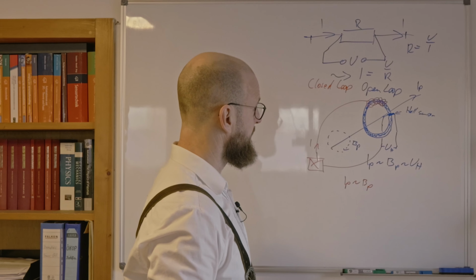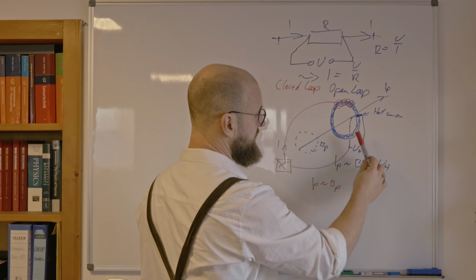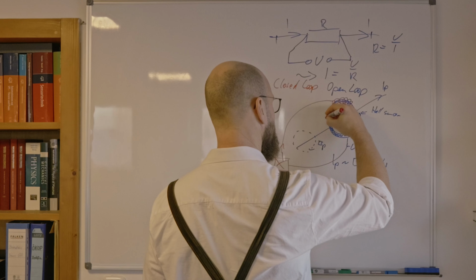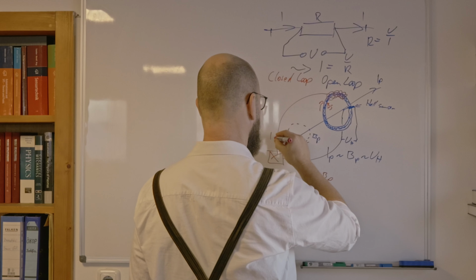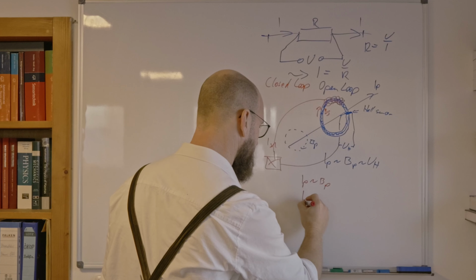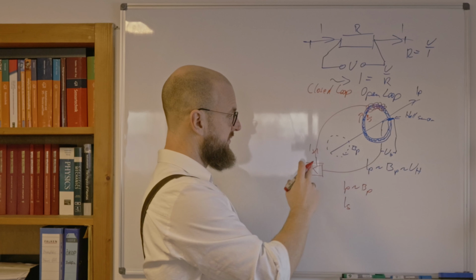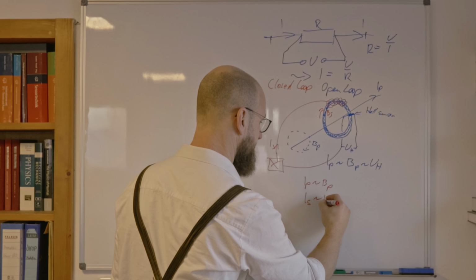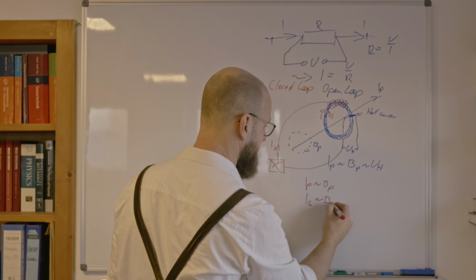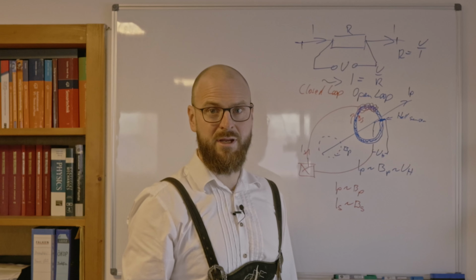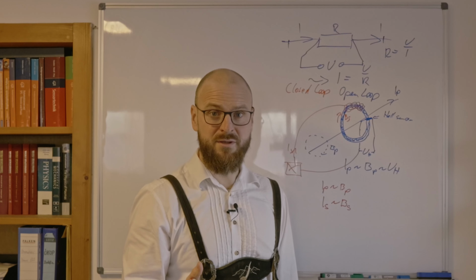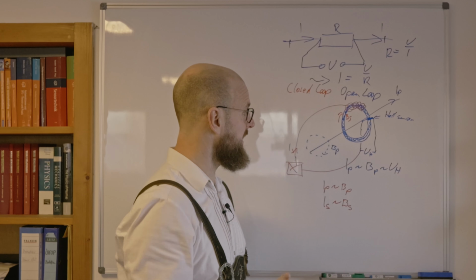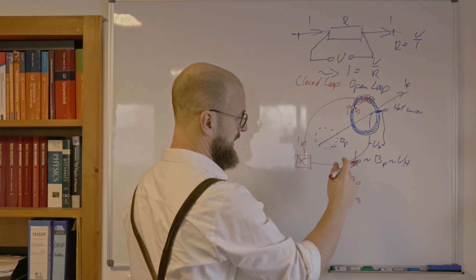Okay, that's great. That magnetic field would induce a Hall voltage over here. And now we start to exert a secondary current over here, which drives the coil, which exerts a secondary magnetic field in the iron ring, which we choose to be the same size, the same value as the primary magnetic field.